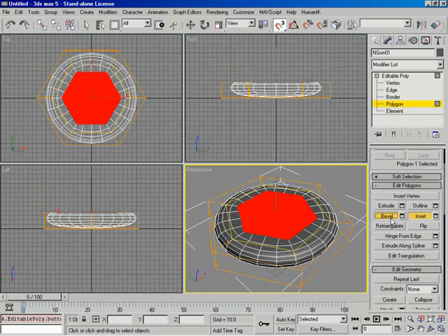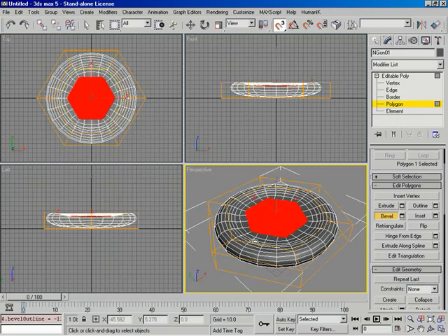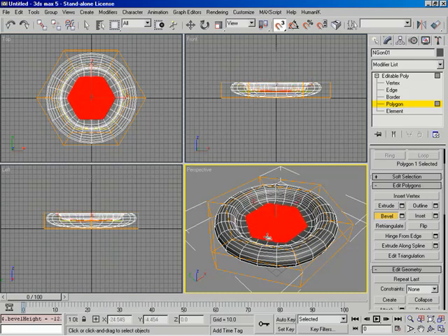And I'll do this by coming over here and grabbing a bevel so that I can do a combination of extrudes and scales at the same time. So again, you notice I'm doing a lot of this interactively. I'll simply click, and I want to come down just a little bit. I'm just determining some thickness here, and I'll scale it inwards. Not a whole lot, maybe right about there. And I'll click to complete. Now I'll do another one, so I'll bring this one down. Maybe not quite so much. And I'll bring this one out.